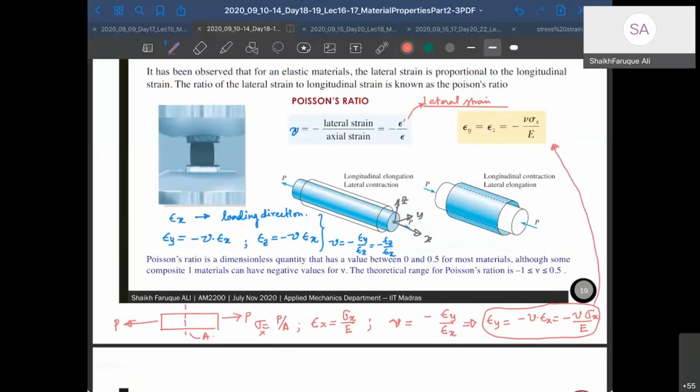So this means that when you give an axial strain along one direction, you will get strains in the other two directions also. They are related, and they're related using Poisson ratio. That's because of the Poisson effect. Okay. All right. Hello, sir. Yes. So it has to be in the elastic limit for deriving this formula. Yeah, because we are using this formula, right? So it has to be in the elastic limit always, right? Yes. Okay, sir.